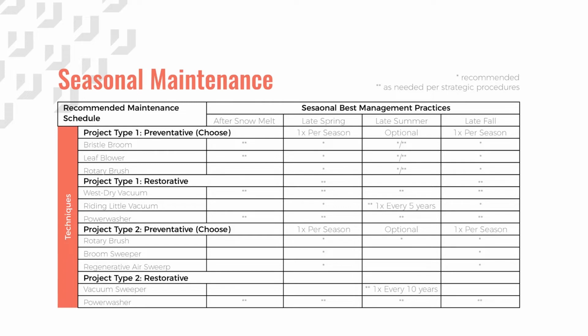Late spring, April 1st to May 15th. Again, use a broom, blowing equipment, or a rotary brush to remove organic material from trees and shrubs. Collect any additional debris, especially from areas that have been mulched or planted with annual flowers. Replenish the jointing aggregate material as necessary.